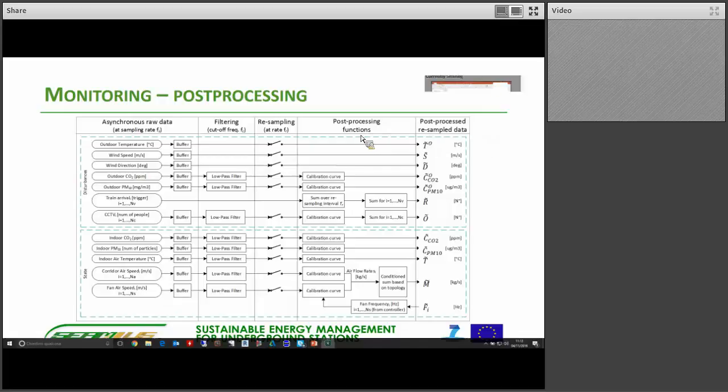One of them is very important: we added to each single data point its reliability, which is an estimation of whether the sensor is working well or badly, so that we can send a signal to the upper module to say that we are not working properly. This was a sort of safety measure explicitly asked by our partner TMB, which is the network manager, and who have to guarantee the safety of their people, the passengers and conductors. So they require us to work in a robust way.